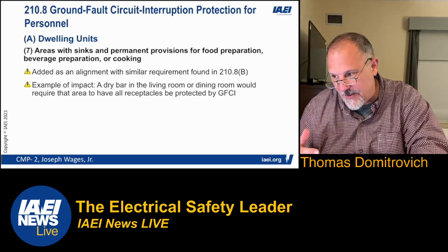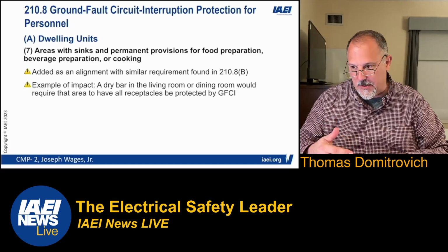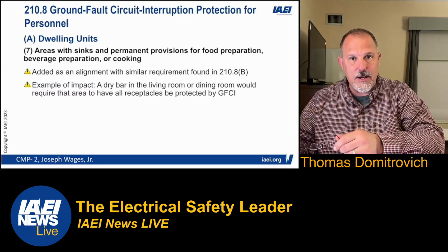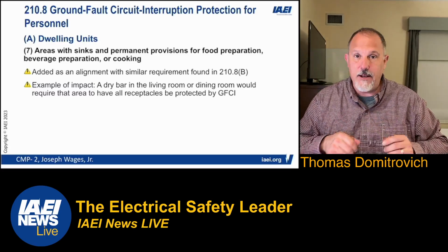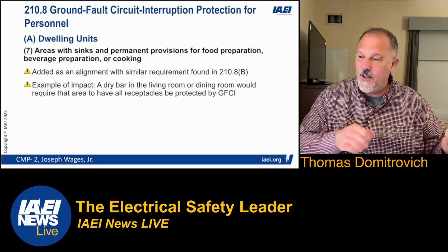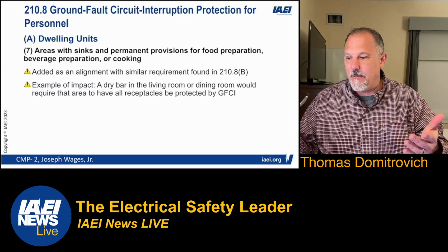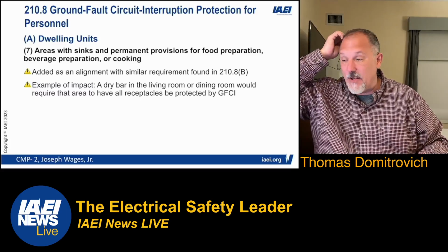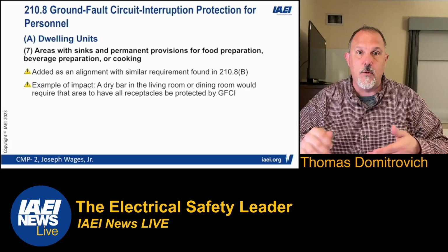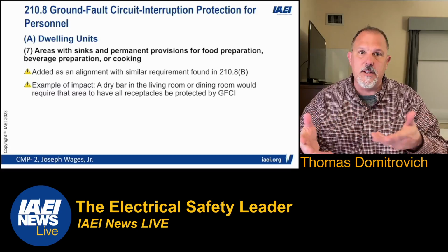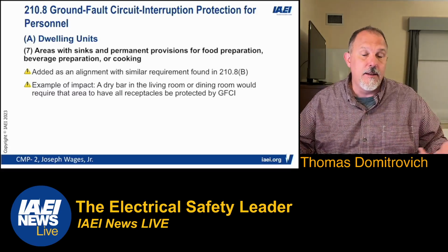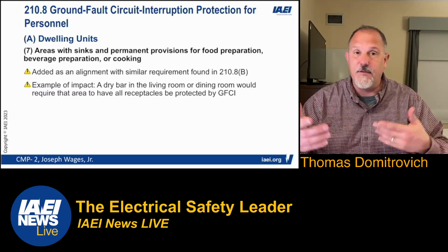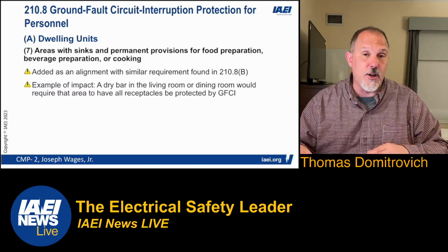So we had an individual and a few individuals who made public inputs that said, why is it a hazard in other than dwelling units and not in a dwelling unit? If I had this same setup, and we give an example of a dry bar, in a living room that might have the provisions for cutting those limes and all this other good stuff, but there's no sink. That would still need to be GFCI protected, because you're using different things there that it could be a shock hazard.